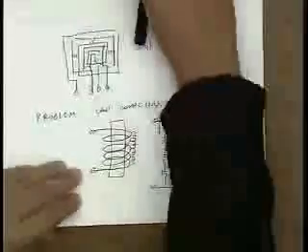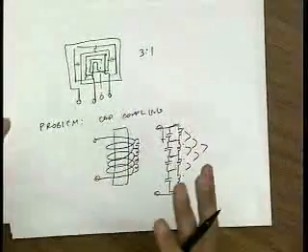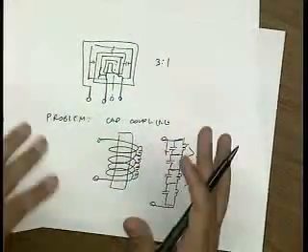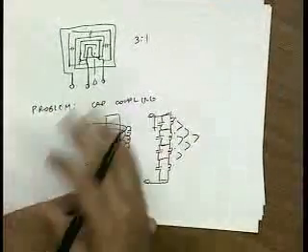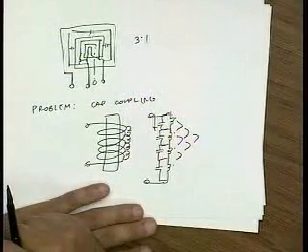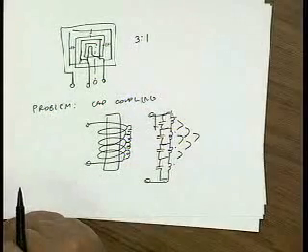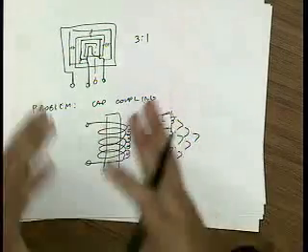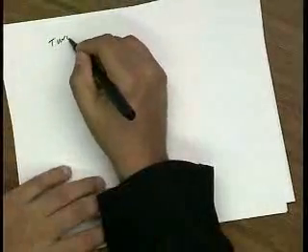Okay? So the problem with transformers is that, one, they tend to be big, and two, they self-resonate at relatively low frequencies. So off-chip, if you have micro-machining technology, you can build transformers up to a few gigahertz. If you don't have micro-machining technology, up to a few hundred megahertz. You can hand-wind good transformers up to a few hundred megahertz. On chip, you can build things actually up to very high frequencies because you can make things so small. But then the amount of inductance you get is limited. So ultimately, you end up with tuned transformers.